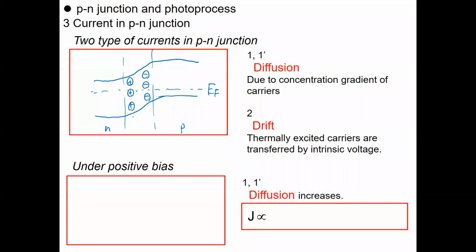So this positive comes from the donor side, the donor gives the electron, and this negative charge is the acceptor level accepting the electrons. I would like to stress that these positive and negative charges are not mobile, because these are the lattice of the donors and acceptors, which cannot be moved. So these are the static charge.